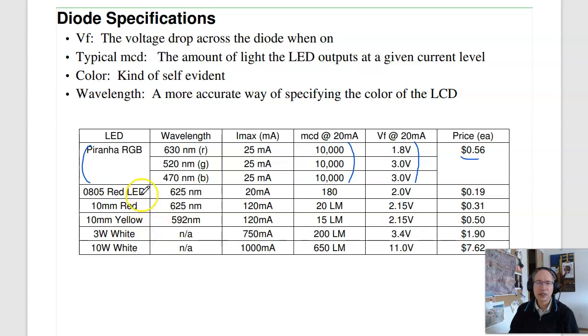The other diodes, like the red, green, yellow. Red isn't a scientific term. The wavelength of light actually tells you, it's a more scientific way of describing it. So this is primarily, or the highest energy is at 625 nanometers, and there's a little bit of variation in it. Like everything, it's a bell-shaped curve, centered at 625 nanometers, and it's actually fairly narrow. It's usually like plus or minus 5 nanometers. 625 nanometers is red, 592 is yellow, I think blue is 470, purple is 400.